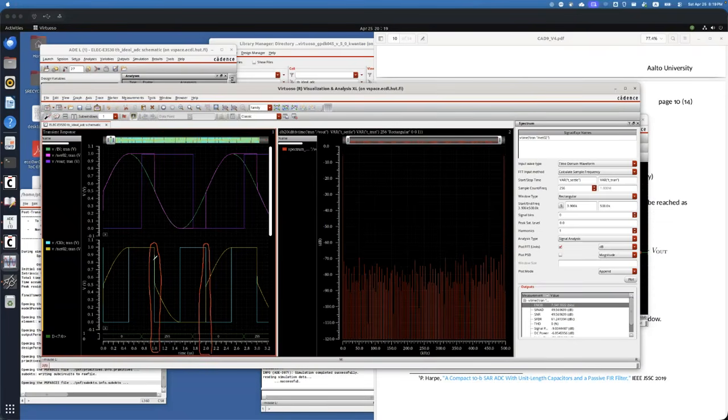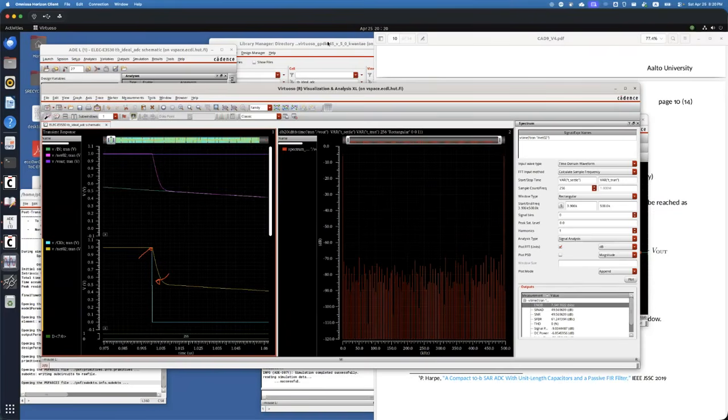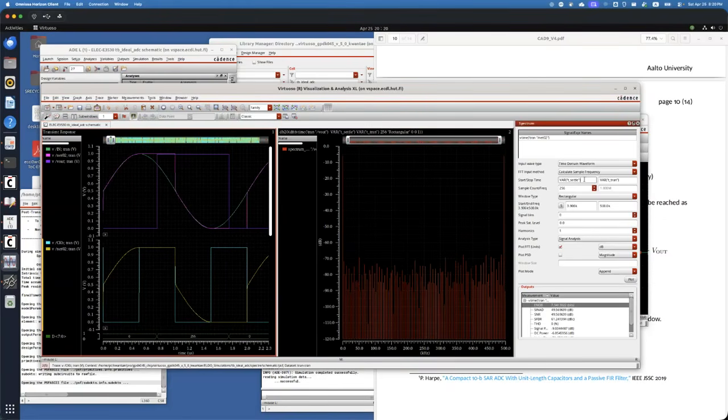But it's not stably settled, because in the vicinity near 1 microsecond, it switches suddenly from here to there. So it may be getting the sample in the middle of switching, here or maybe here. It is a slow switching in this way. What I mean is that it will be better, or safer, to set some more delay.